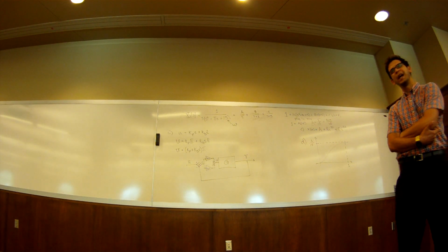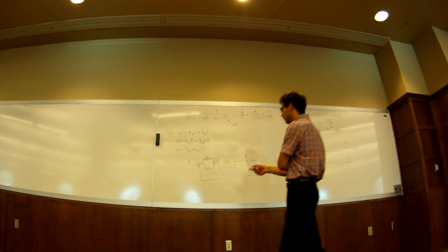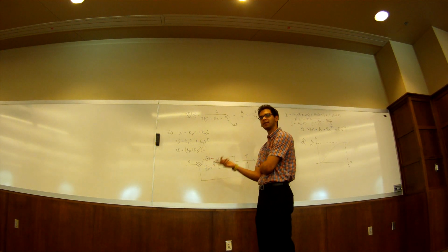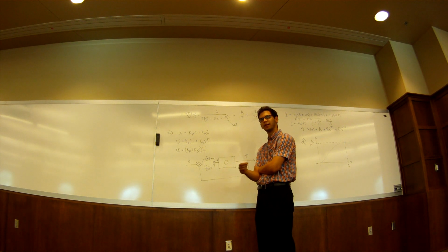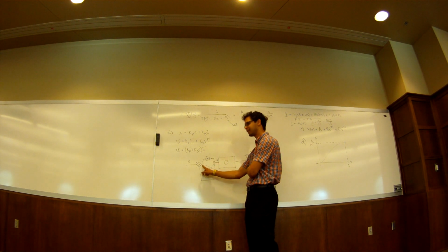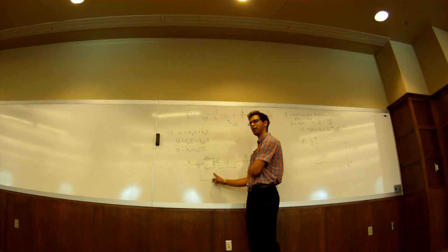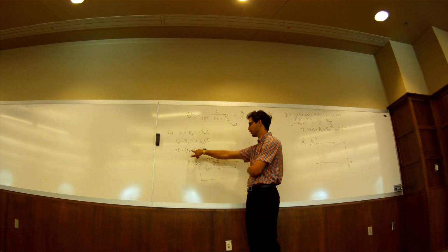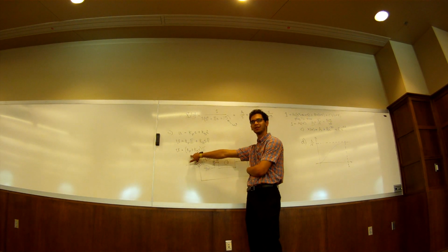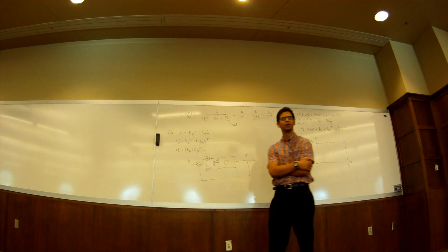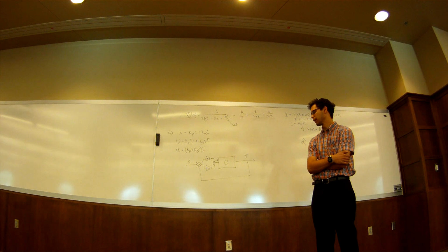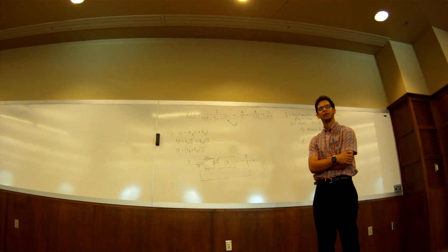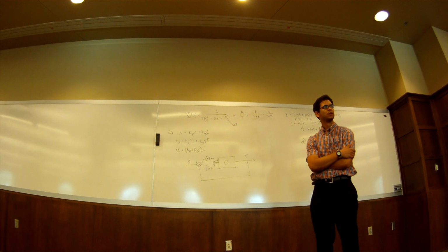If you left E inside these blocks, and when you reduce down your block diagram you had E in the numerator, that's not quite right. E is a signal and it's multiplied by this block. The actual transfer function block is this term, and that gets thrown into here. That's an important thing I think a lot of you miss. So this is PD control.